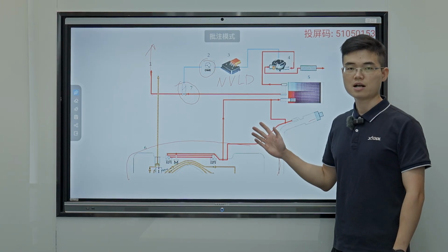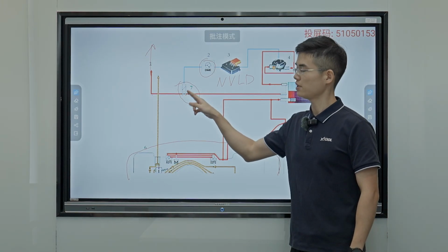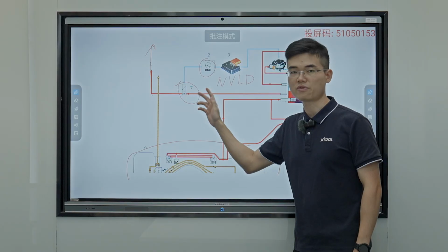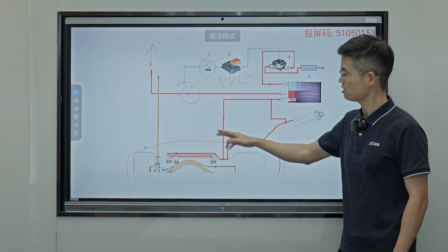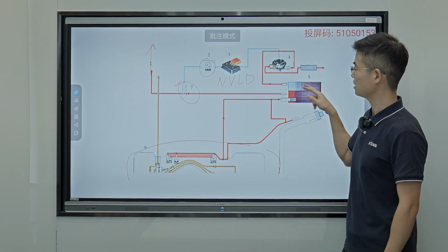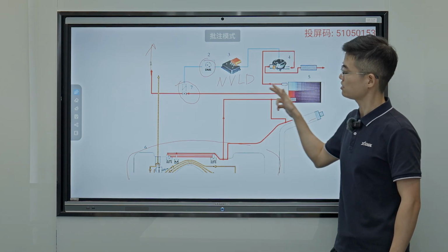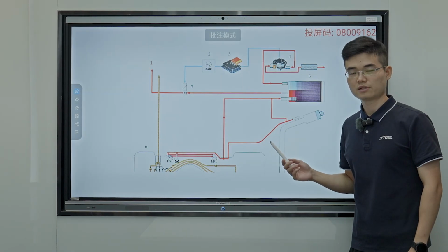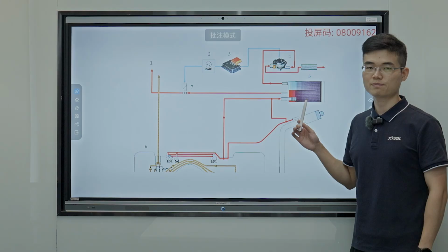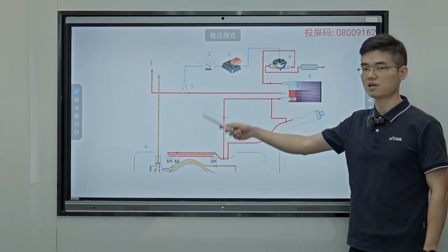In the end, I must mention that the fuel tank vent valve is closed when there is no power supply. It's very important because it can prevent the fuel vapors from the activated carbon filter from entering the motor's intake manifold. At last, I will summarize the possible leakage points in the pipeline system.